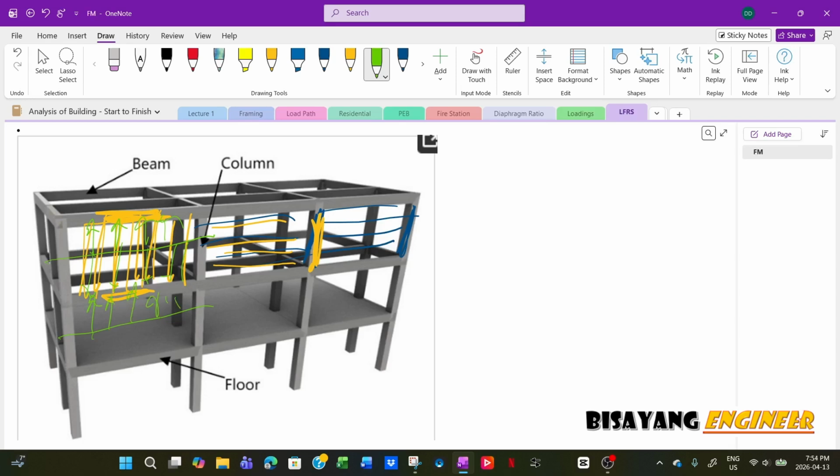So when you analyze this, if we draw the schematic diagram, this is the roof beam, this is the floor beam, and there's another floor here, and then probably a footing here. So that means if you are using, say, steel studs, or if we are using hollow block, it depends. Like hollow block, usually it is supported, you have the main vertical bar for the hollow block, so that means all the loads are transferred to the beam.